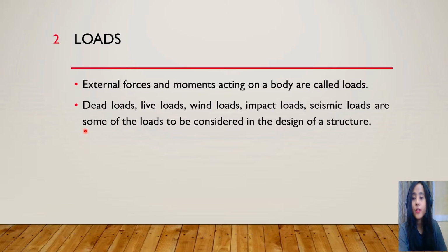So first, if we talk about dead loads, the dead loads include loads that are relatively constant over time, including the weight of the structure itself and immovable fixtures such as walls, plastered board, or carpet. The roof is also a dead load. Building materials are not dead load until constructed in permanent position. So dead load generally consists of permanent loads, which come under self-weight of the structure itself.